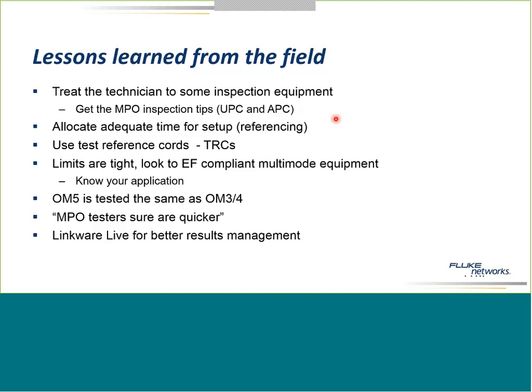You're going to need that APC tip. Get enough time set up to set your reference. We saw that if we're setting a reference to run a trunk cable through a regular OLTS with just one output and one input port, it's going to take us some time to get that reference set up, but we really want the reference to get set properly.